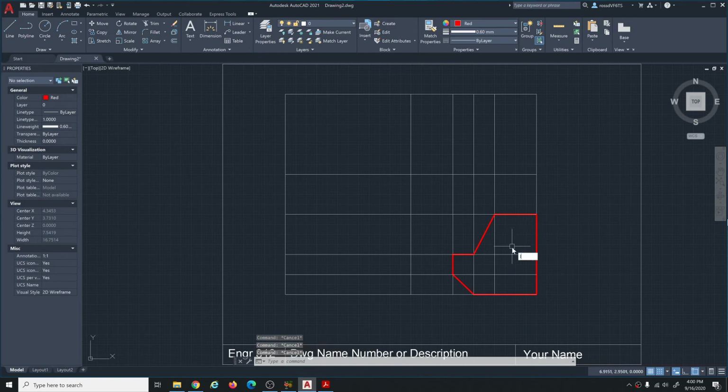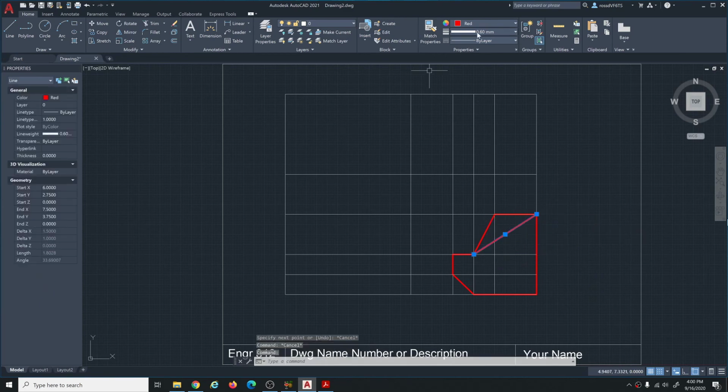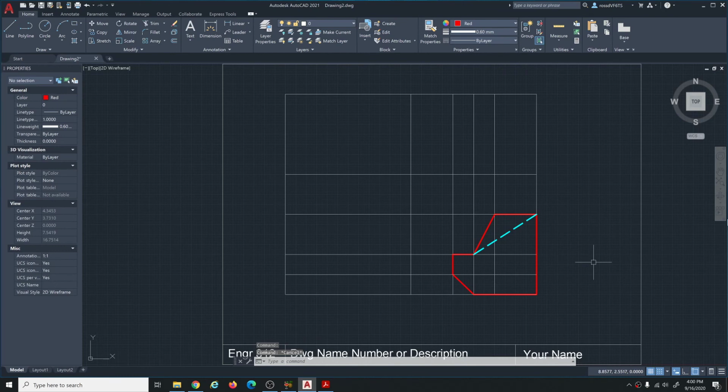Now, while I have this up, there's a line that goes here to here, but it's hidden. I just drew it, and then I'm gonna go back and change it to hidden. There's that. That's the end view, pretty much done. Okay, let's do some more offsets back on the other two views. So we'll offset 1 inch. This guy that away, and this guy that away, and I think I can heavy that in now, right?